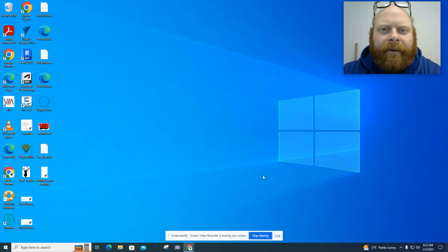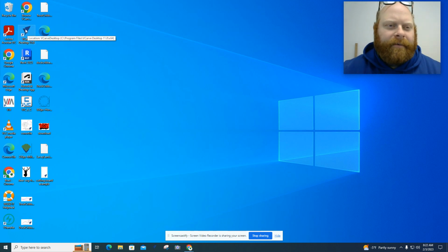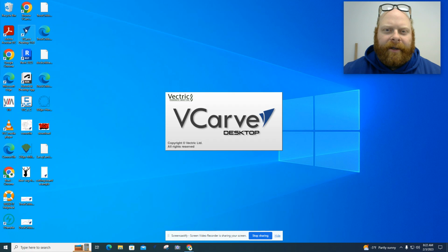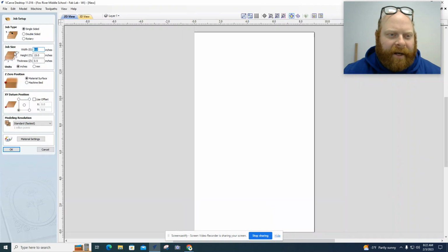Hey, making a quick video here with you guys to show you how to do the cutting boards that you're doing on VCarve. So first thing you need to do on your computer is find where you have the VCarve account or the software. So here it is. You're going to double click it to open it up. And then from here, you're going to create a new file. So you click here where it says create new file.